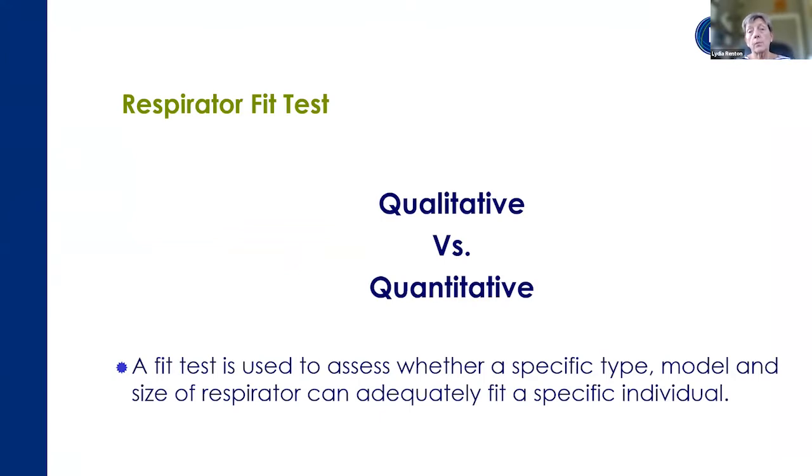So, talking about respirator fit tests: again, they need to be carried out by qualified persons. A qualified person means not only knowledgeable on the respirators, but also on the methodology they're using. Whether it's qualitative or quantitative fit testing, they need to know the equipment or instrumentation they're using, how it works, how it can fail to work properly, and how to do checks on it.